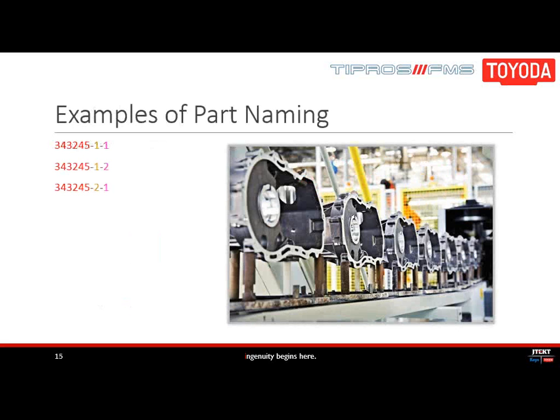So as an example, here we have a part with 2 operations and 2 processes. So in the first example, this would be the first operation for a part. An example might be a part that's clamped to a fixture using toe clamps. You then go ahead and drill holes for screws to then hold the part to the fixture in a separate process. Building on that, the second example, this would be the first operation of the second process for that part.